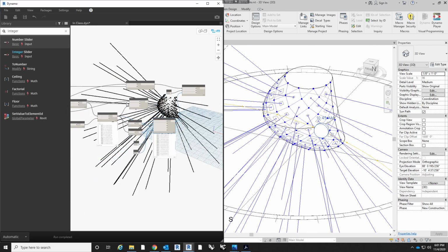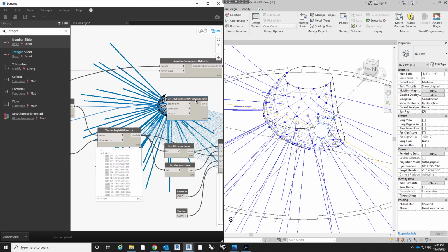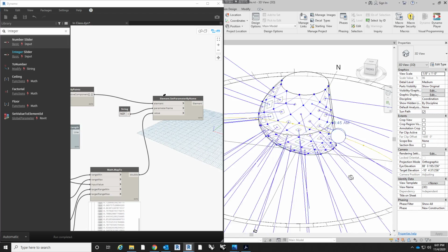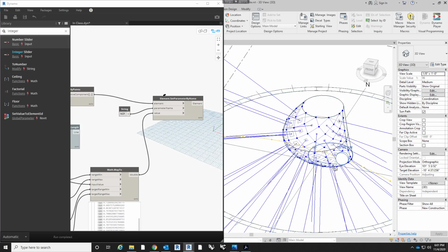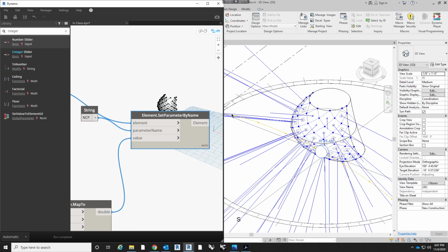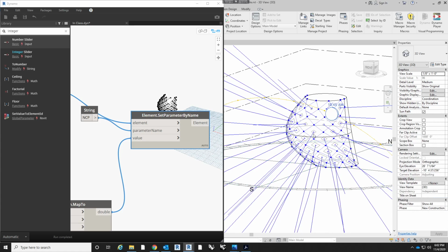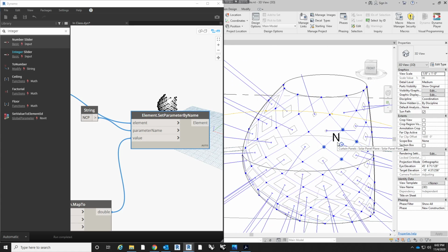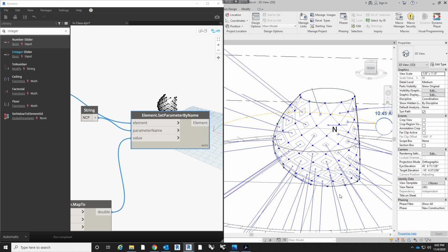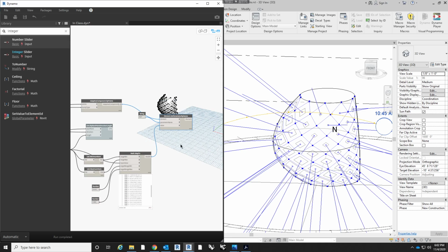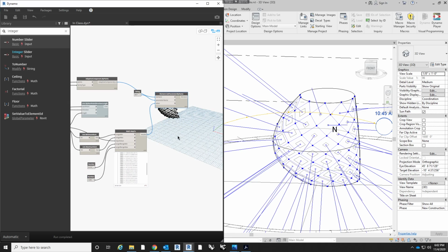And then if you look, we can probably go in and hide the visualize. There it is, the start point direction length. If we hide that, of course, for some reason it's not going to hide it here. But now our panels are being influenced directly by the sun, and it looks like it's doing the opposite of what we want, right? If you had an actual facade system on your project, you'd want the shading panels to be as large and as opaque as possible when it's in the direct path of the solar radiation, and you want it to be open in non-direct sunlight.